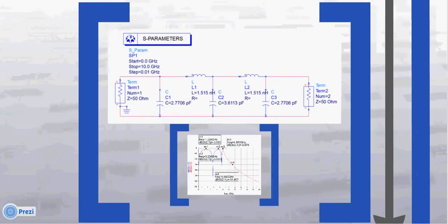We then designed a low-pass prototype filter by finding the N value by looking at Pozar's 3 dB equal ripple prototype on figure 8.27b. The N value was found by choosing the curve that satisfied a calculated normalized impedance and -30 dB attenuation. The N value that we got was 5.